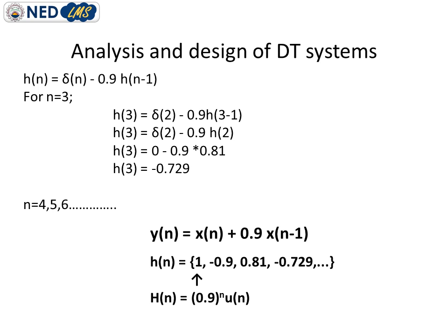Now we further vary n is equal to 3. You can see we have to put the impulse response we obtained in the previous step, which is at n is equal to 2, and we obtained 0.81. This 0.81 will multiply with 0.9, and you can notice that here is a negative sign, so the overall answer will become negative.